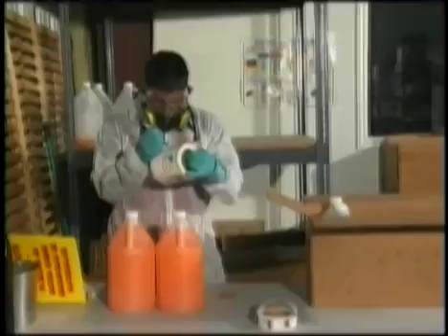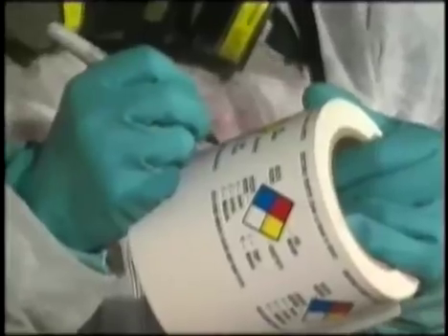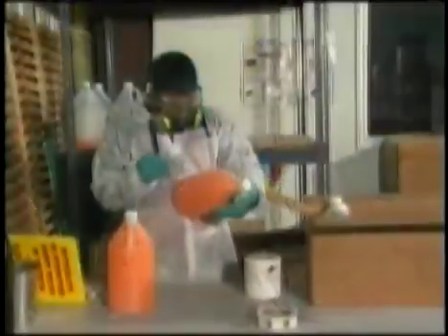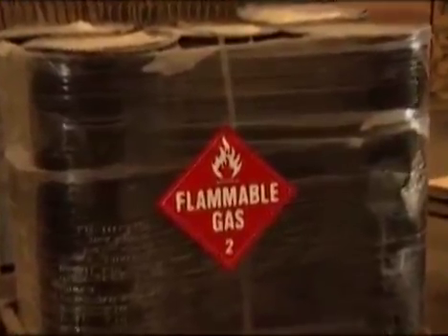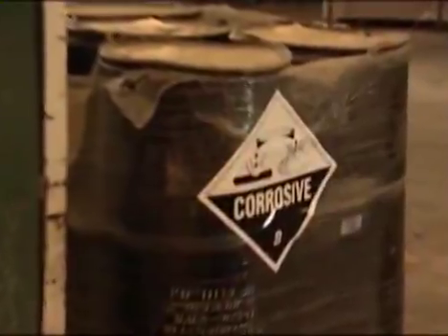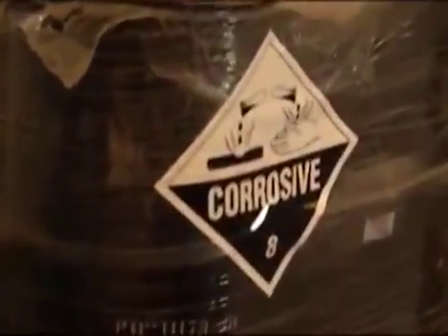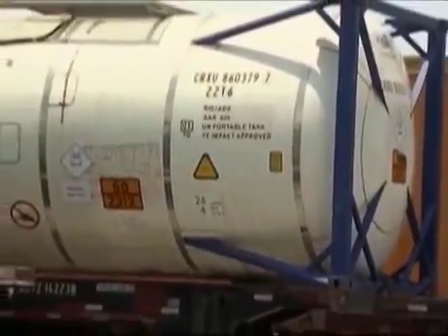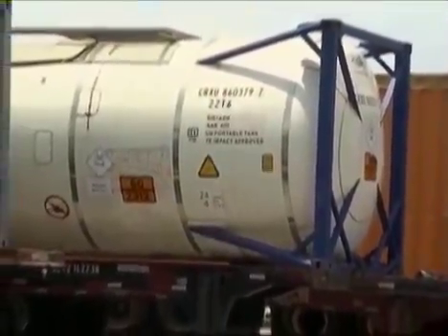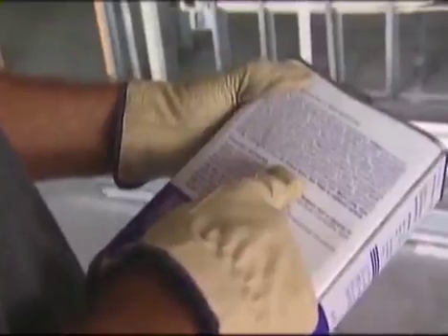If the hazardous chemical is subsequently transferred by the employer from the primary container to a secondary container, the employer must label the secondary container. Employers are responsible for ensuring each container of hazardous chemicals in the workplace is labeled, tagged, or marked with the appropriate information. Workplace labels must be legible, in English, and prominently displayed on the container. Other languages may be used as long as the information is presented in English as well.